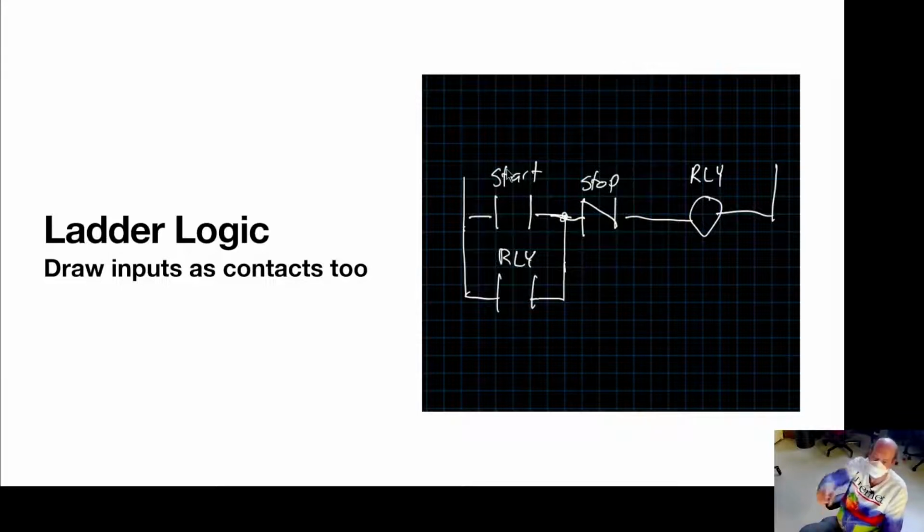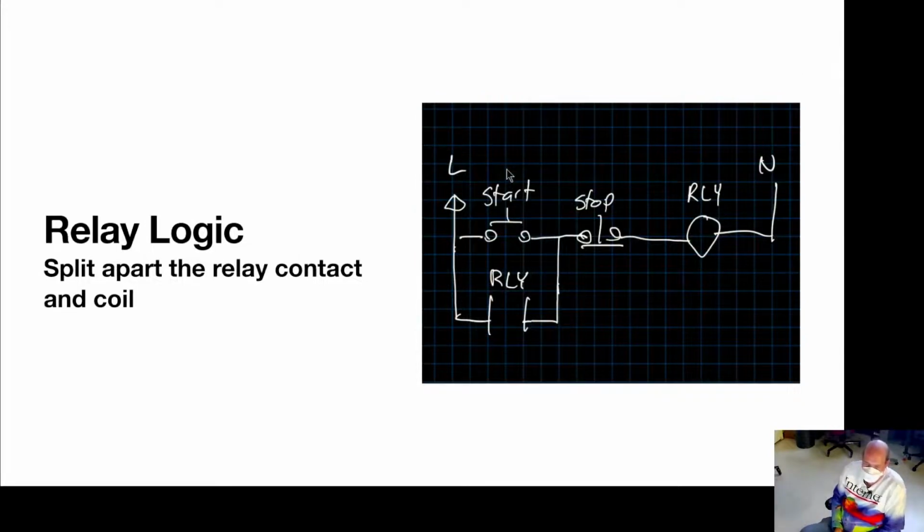So we have a question, by the way. In this diagram, how would you define a relay versus a capacitor? Is it just distance between the two elements, or are these two entirely different schematics? I'm transitioning from an electrical schematic to a logic schematic. Got it. Okay. So it is very much the same shape, but the spacing between the two lines is a bit further apart on a relay contact than it is on a capacitor. Got it. Thank you.